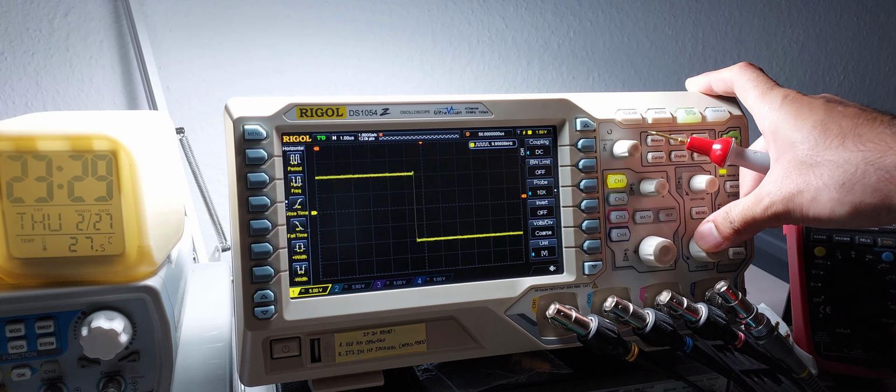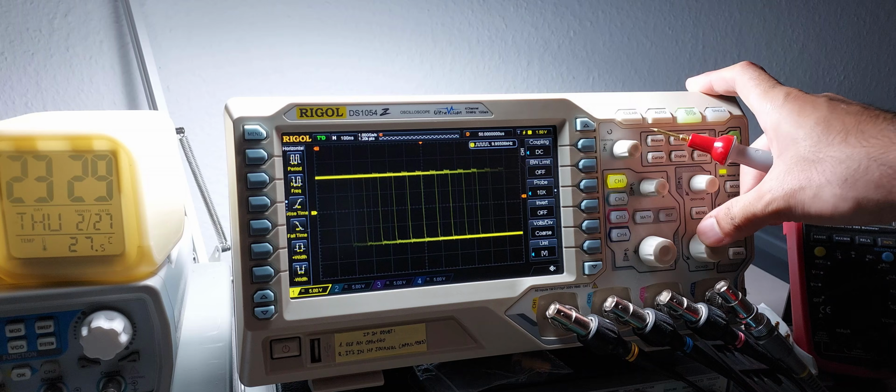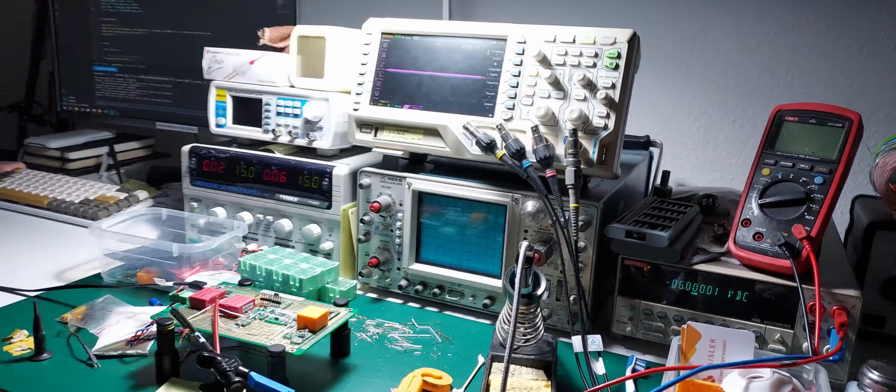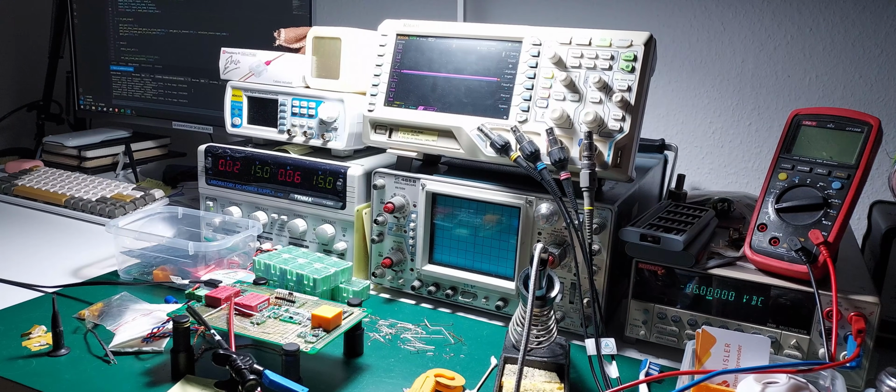The result is perfect modulation. The center values occur more often than the extreme values depending on the fractional counts. The effective PWM resolution is around 21 million counts, despite the wrap value only being 1200. The fun does not end here. Now that the resolution of the DAC is much higher than the INL error, correction is a real possibility.